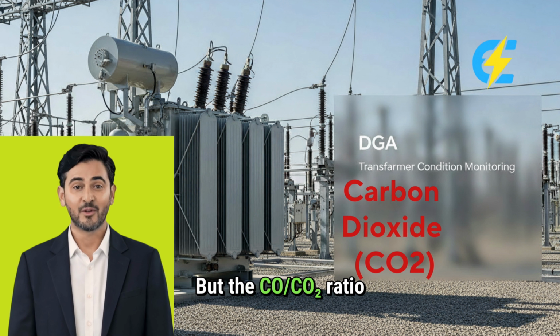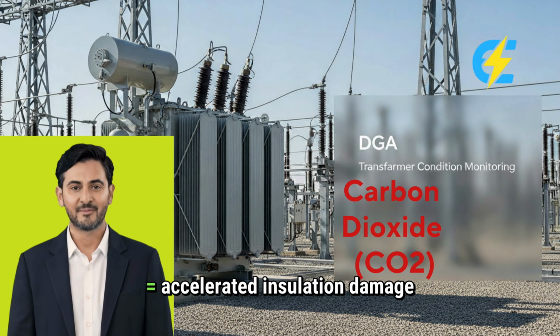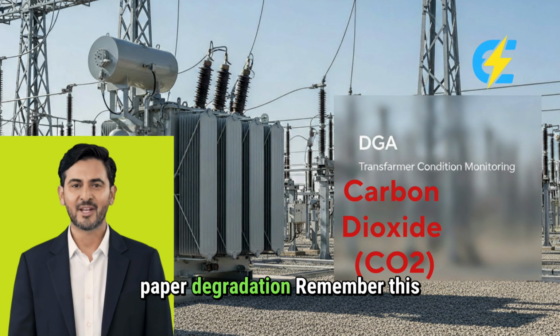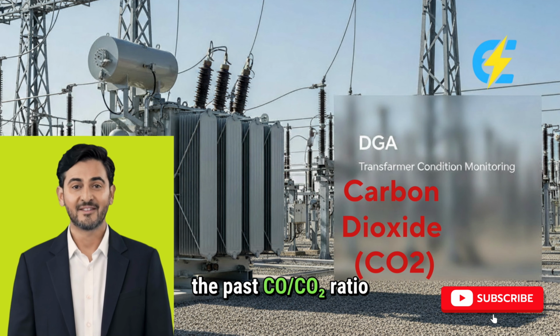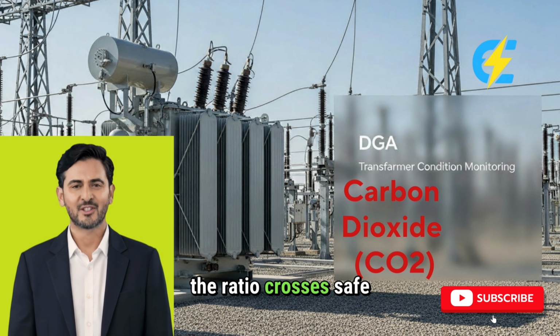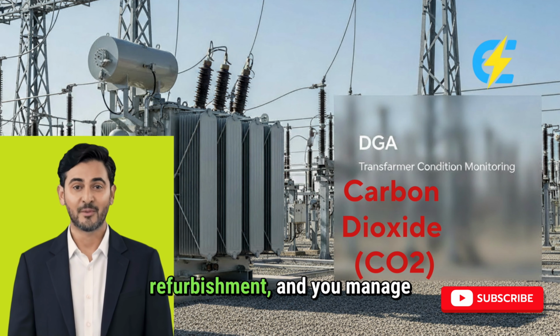But the CO-CO2 ratio tells you the condition. Low ratio, aging stable, normal aging. Rising ratio, accelerated insulation damage. High ratio, active paper degradation. Remember this golden rule. CO shows the present, CO2 shows the past, CO-CO2 ratio shows the future. When the ratio crosses safe limits, you don't wait for failures, you reassess loading, you plan refurbishment, and you manage remaining life.